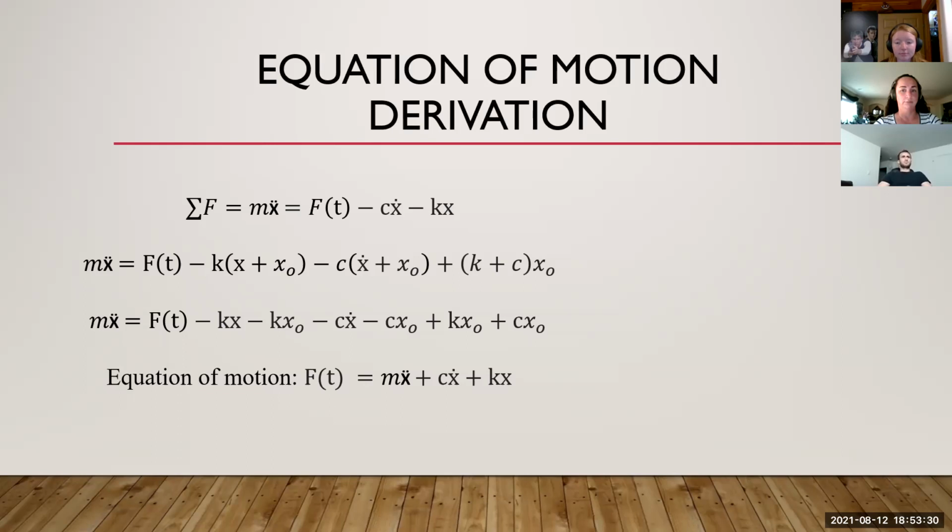Here, the derivation process can be seen, showing how the forces were summed and applied in order to arrive at the equation of motion. The equation is a force as a function of time equal to mass times acceleration plus damping times velocity plus spring stiffness times displacement.